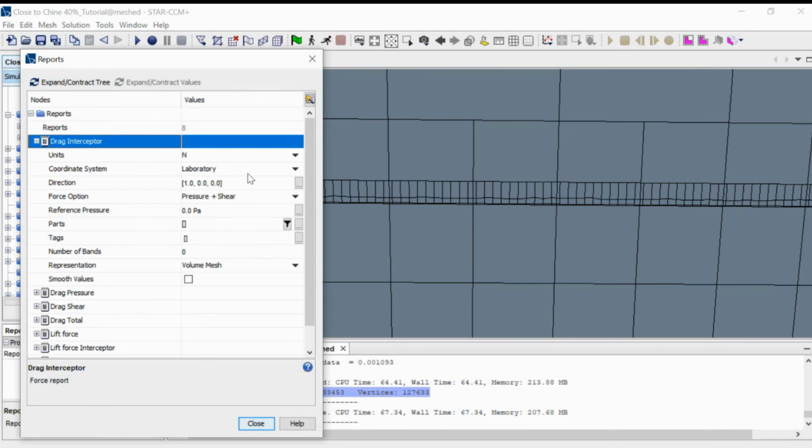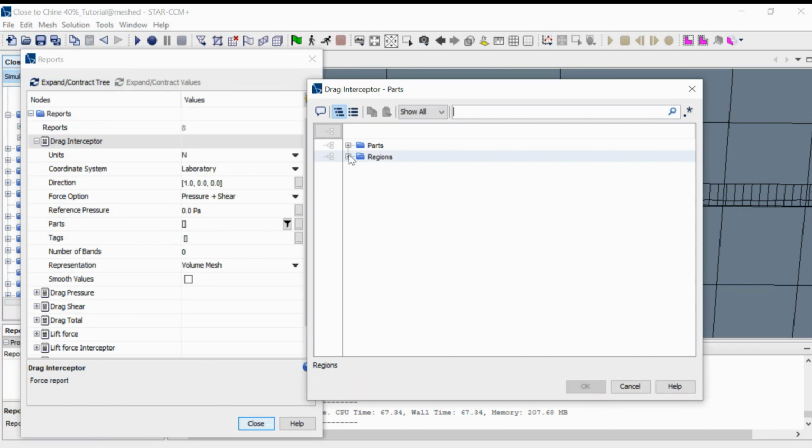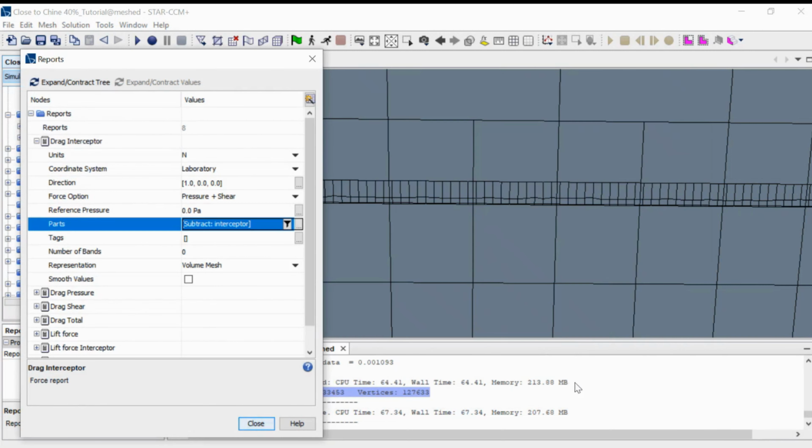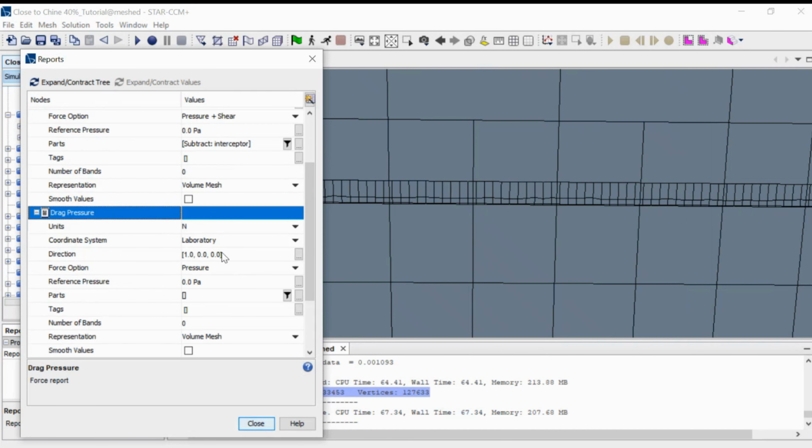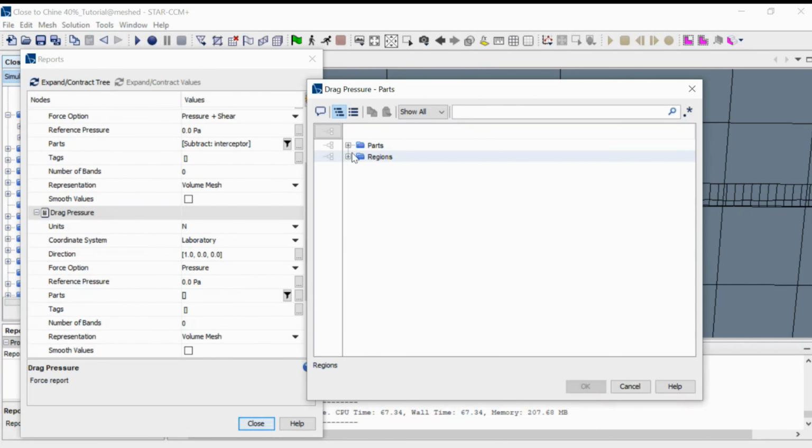A report presents a computed summary of the current simulation. The report summaries are usable for post-processing and enable engineering quantities such as drag, lift, trim, heave, or mass flow to be computed.